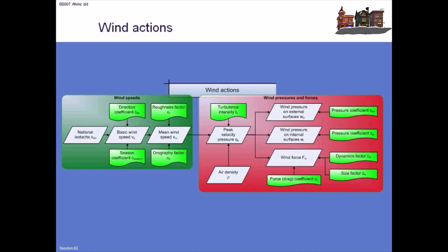and we then take the gust pressure, and if it's a bridge, then we'll apply a drag coefficient to calculate the overall force on a structure. If you're a buildings engineer, then they typically take the gust pressure and apply pressure coefficients, so you can design for forces on cladding in different parts of the structure. But we go down the drag coefficient route. And the next couple of slides, I think, will show typical drag coefficients, where they're almost identical to what we had previously in British codes.